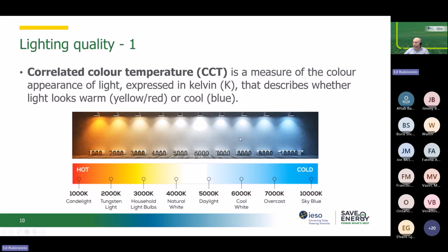If it's more of a sterile environment, maybe a hallway or something utilitarian, you're probably going to tend more towards the higher numbers. So what's happening in that space is a big determinant of the lighting quality you're aiming towards. Also, keep in mind that higher temperatures, the bluer, whiter colored lights, appear brighter, which is an important part of designing lighting systems.